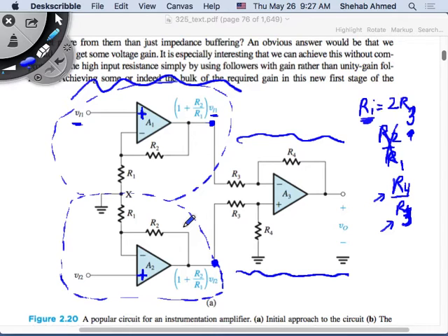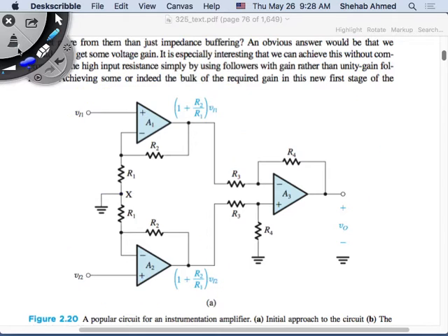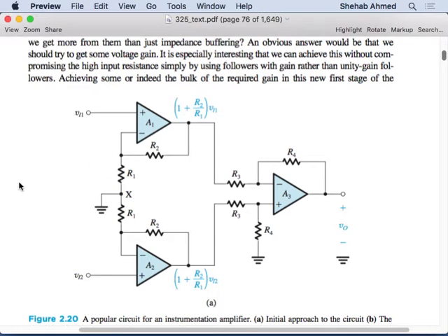So we dealt with the input impedance, and we dealt with the common mode in two funky ways, right? Nice, bad, it's okay, but not a great way. So does everybody see the limitation of this circuit? We went away from this circuit and introduced a small change. All we did now was remove this ground and make these two resistors one resistor. Let's see what that buys us.